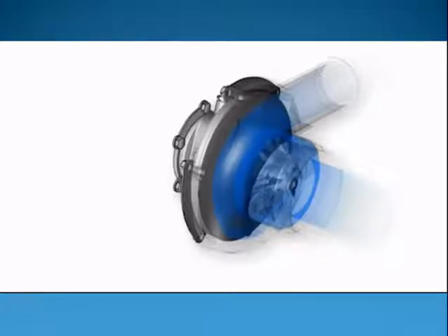The air is routed out of the compressor impeller radially and is routed into the diffuser. This is where the speed of the air is reduced largely loss-free. The consequence of this is that pressure and temperature rise. The diffuser is formed by the compressor rear wall and a part of the volute casing. The air is collected and the speed is further reduced as far as the compressor outlet in the volute casing.